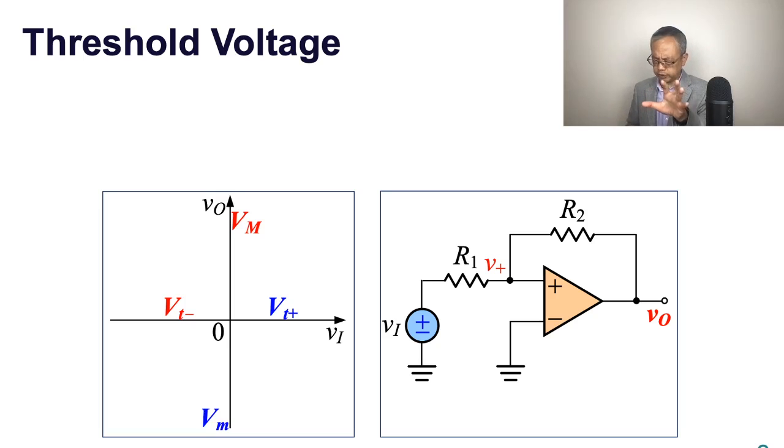The key takeaway, the learning objective, is you are able to harness this circuit to handle the transfer characteristic, which is nonlinear. All right. The nonlinear transfer characteristic of this bistable multivibrator, VO versus VI. Because the nature of the positive feedback tells us there are only two stable states: VO capital M, V capital M, the red state, or the blue state, V lowercase m.